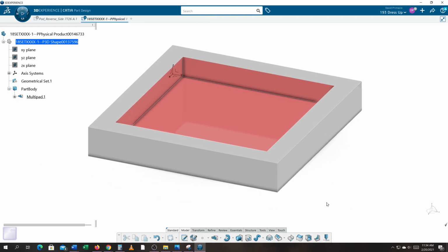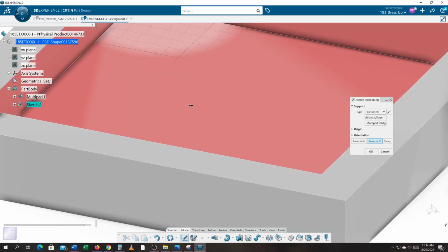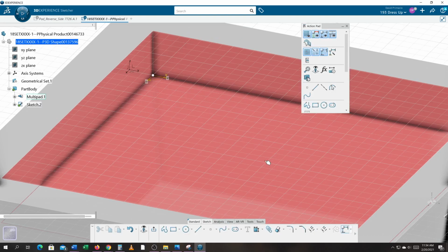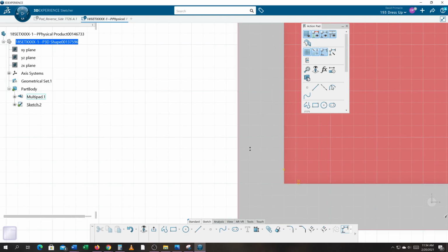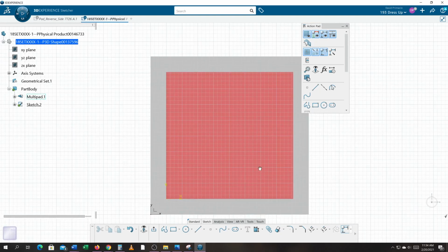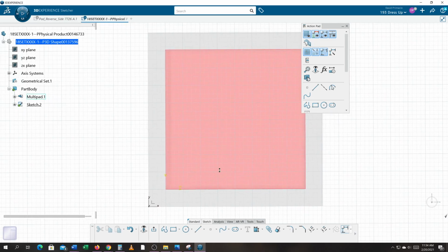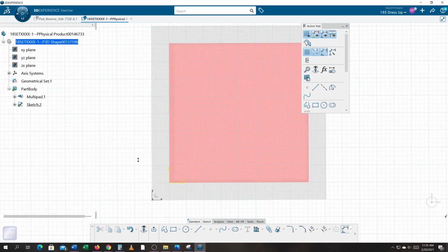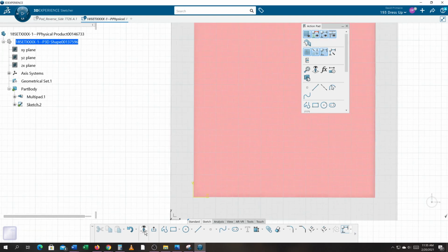Okay, now to create the spline, what I would do is I would do my position sketch. Under position sketch, make sure that this is off so that you can grab a horizontal line and a vertical line. I'm going to reverse the vertical so my axis looks like this in the corner. Select OK. Let's go normal to view. Oh, what happened? I deactivated my part somehow. Let's go normal to view again.